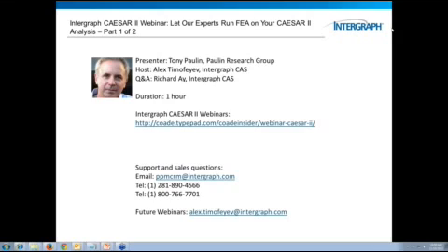I tell you what, that's a great question, and the only codes that we focused on so far, as you say, Mandeep, have been the EN code and B31. So I haven't looked at any of the other codes per se to see if they've got the more applicable data as part of the text. I mean, the other codes definitely have the same equations for SIFs, but you would also like it that they use the more applicable data terminology also. So I guess my answer to that is I don't know for codes beyond B31 and EN.